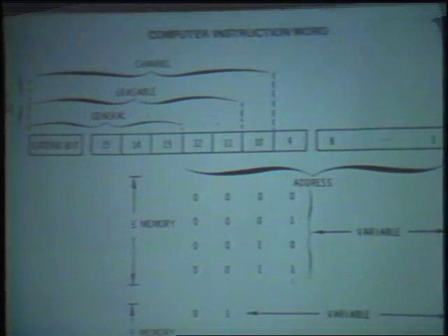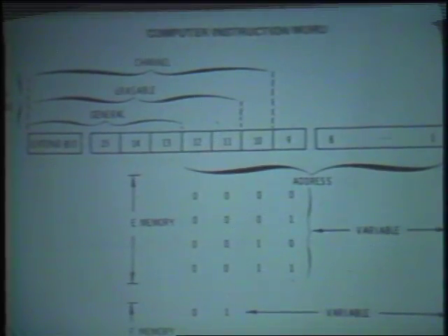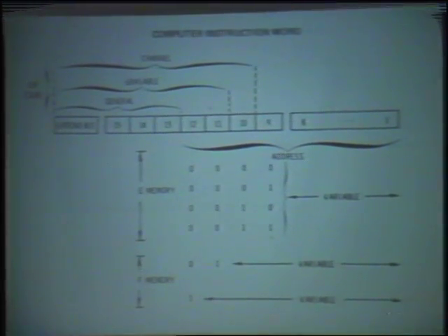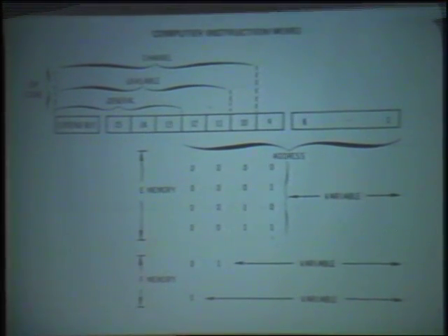The data and instruction words in the memory are 15 bits plus parity. Data is represented as a 14-bit binary word plus the sign bit. Double precision operations were provided to supply 28-bit computations. The instruction word contains the address and operation codes for the computer operation. The primary 15-bit word is here.